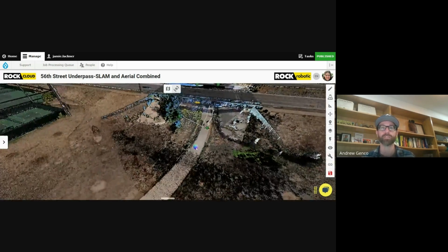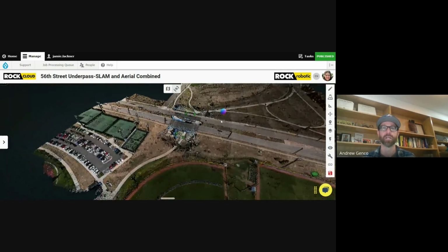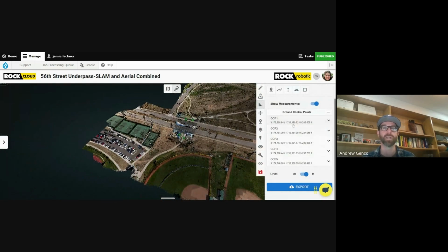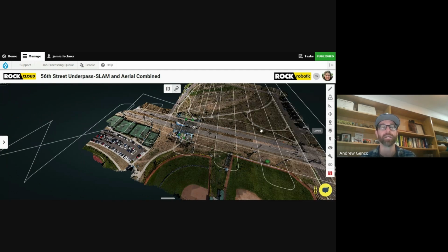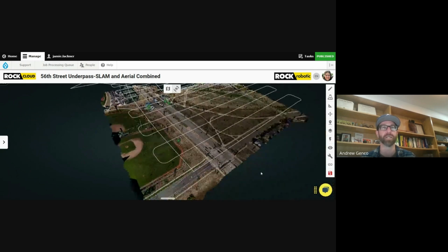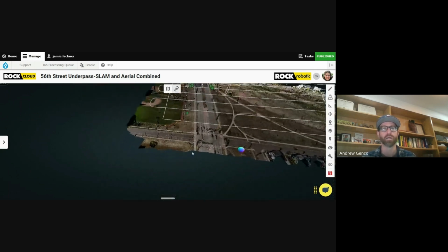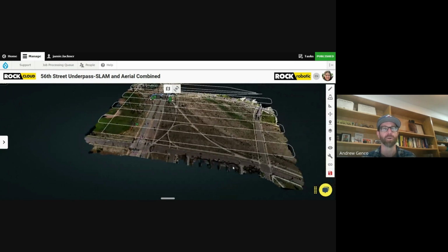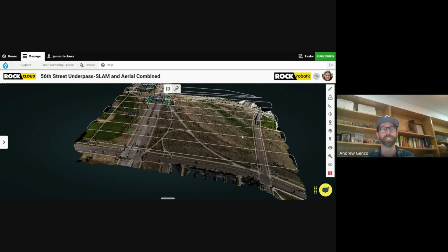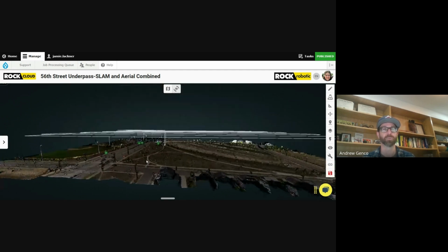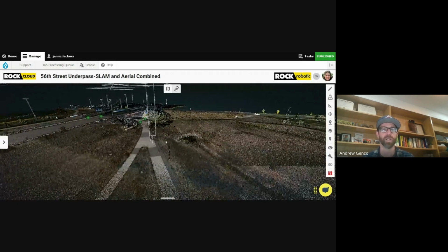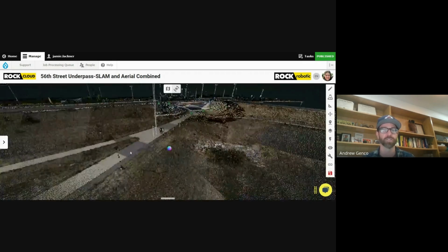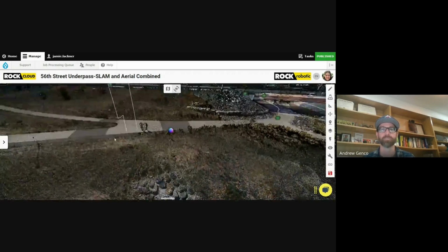Now, moving into the airborne mission planning considerations. We want to determine if terrain following is needed for the survey area due to the topographic variation that may be present. In this area, there was topographic variation present. It wasn't on the order where it was determined terrain following was needed. But what we did do is reduce the flight height of the drone, because we took off around the midpoint of the survey area, just to make sure that in the areas of lower topography, the drone wasn't going to be too far off the surface and cause reduced data accuracy.